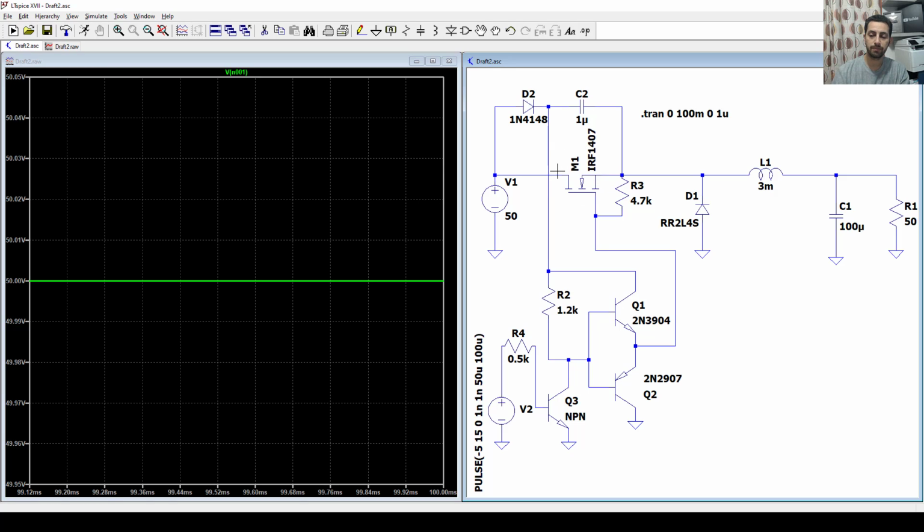But once this MOSFET turns off, if we turn on that transistor here, we take all that charge to the ground. And once this MOSFET turns off, that capacitor now has time to recharge again. And that recharge comes by this diode. Now that diode will push some current toward that capacitor, and the current also will complete the cycle toward the ground by this diode.